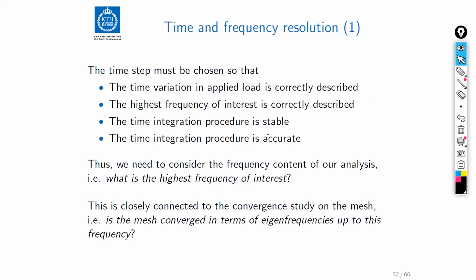So it's very important to think about the highest frequency of interest when we set up an analysis like this. It can have different implications on the analysis, depending on how we solve the equations of motion. And again, this is also connected very closely to the convergence study that we do on the mesh. So we have to make sure that the solution is converged in terms of eigenfrequencies up to that highest frequency.